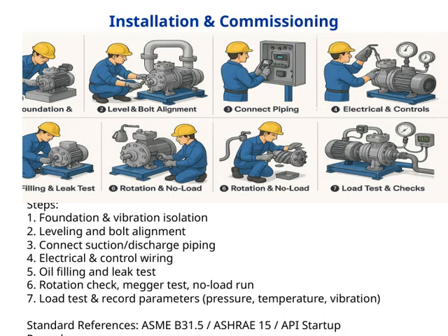Now, let's walk through the final step, installation and commissioning. First, we start with the foundation and vibration isolation. It's crucial to ensure the base is solid and properly isolated to prevent any operational vibrations from affecting performance or causing damage. Next, we move on to leveling and bolt alignment, which are vital for smooth operation and to avoid undue stress on the equipment.